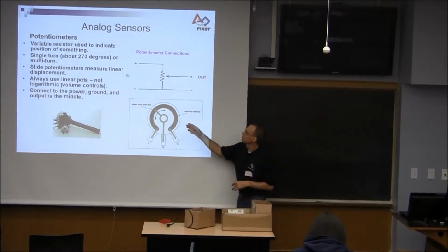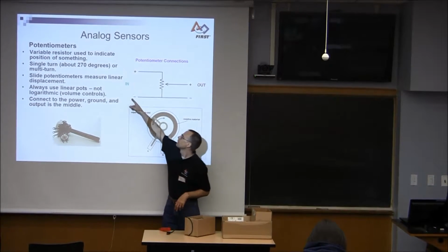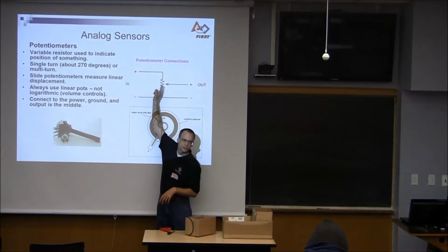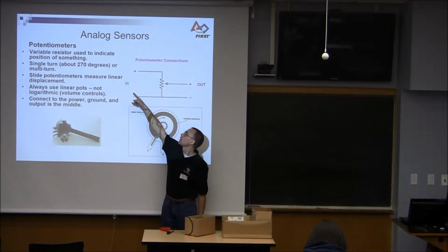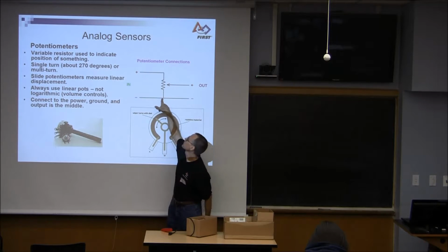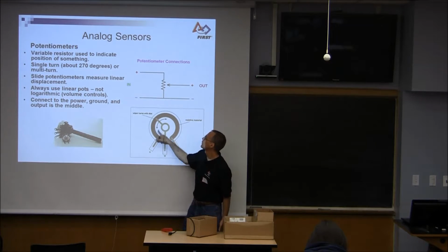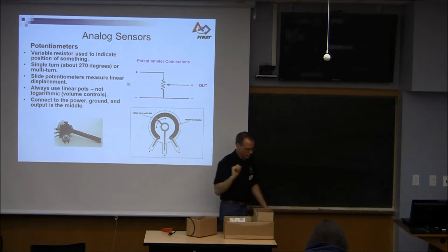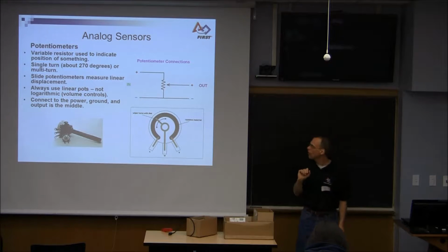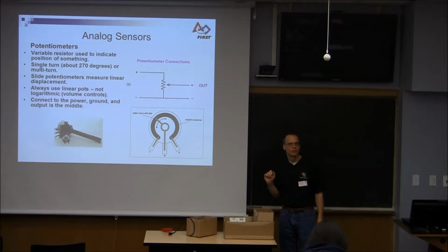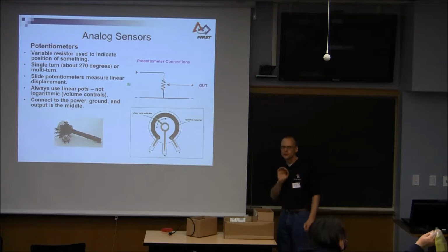When I show this diagram, the "in" is hard to see, so that's the 12 volts or the 5 volts from your robot in, and it goes across this element, which is represented here, and it goes right to ground. And I've had students say, well, Mr. Hall, that's a short circuit, isn't it? Yeah, it is. But do resistors resist voltage or current?